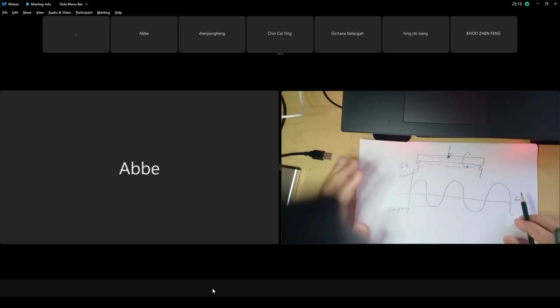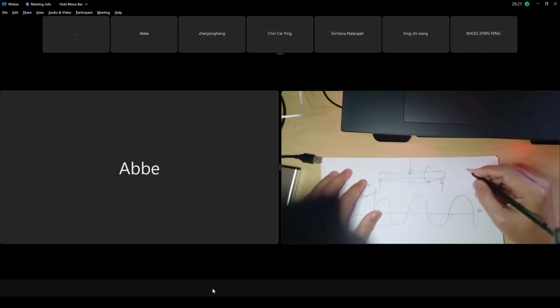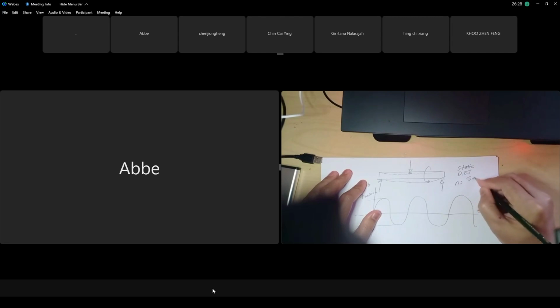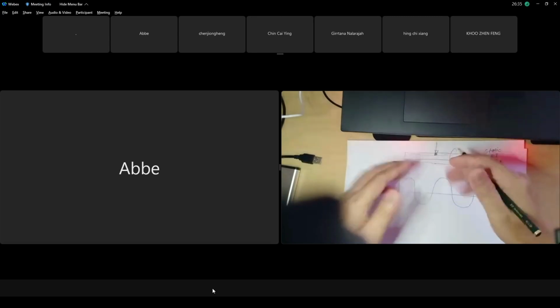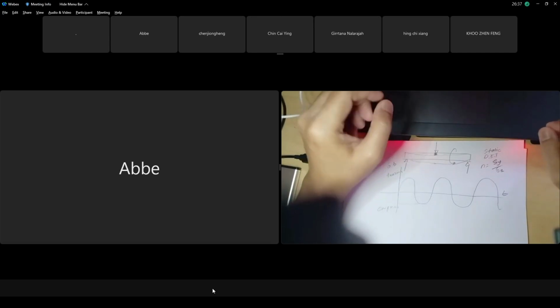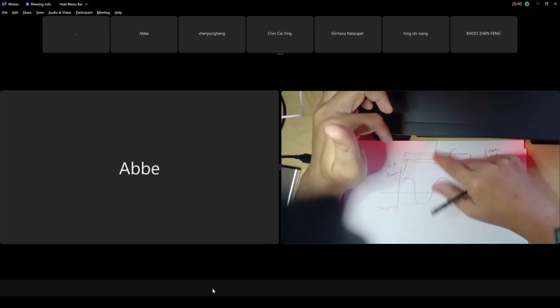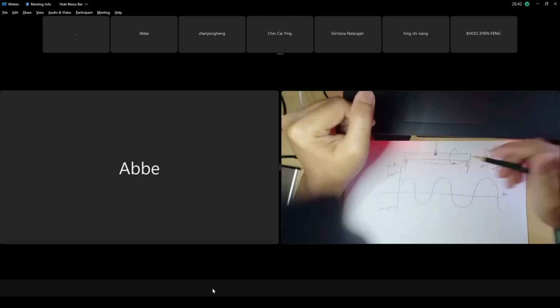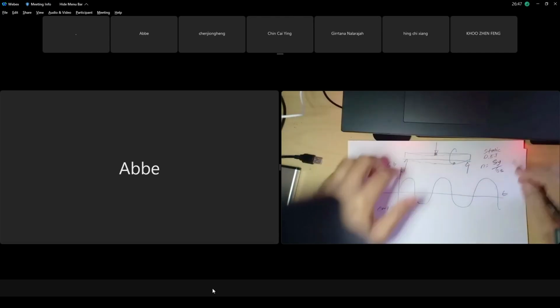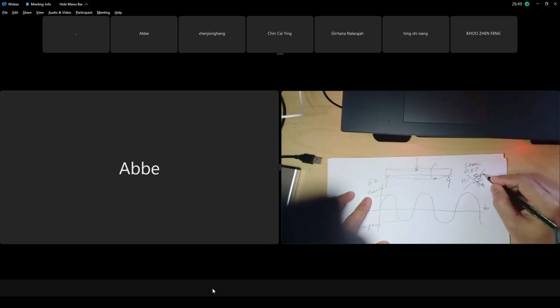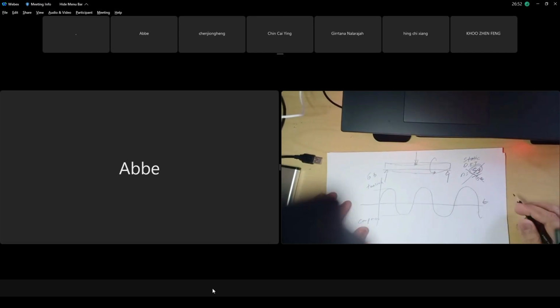So if this is the case, remember when you do safety factor based on static entities, and you use DET theory, your safety factor is SY, your yield strength, over sigma E. That is static. But actually the shaft is rotating. If the shaft is rotating and you have a bending load, for example pure bending, your element will face tension and compression through time. So we will no longer use static energy because our strength of the shaft is no longer SY.